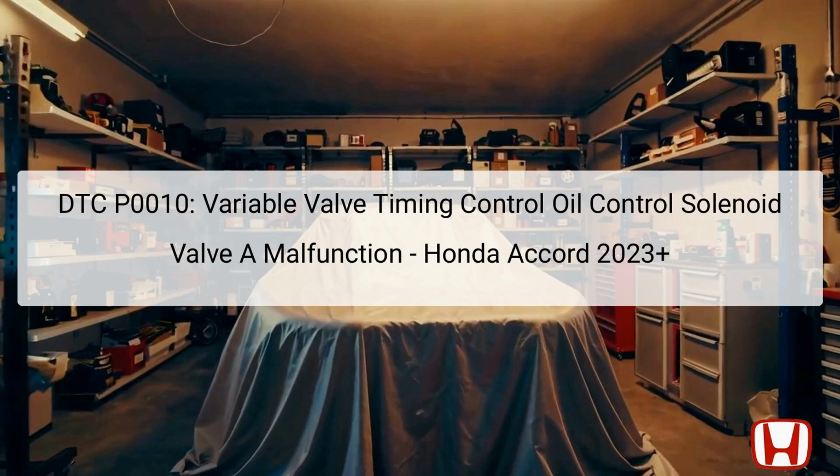DTC P0010 indicates a malfunction of the variable valve timing control (VTC) oil control solenoid valve A in the Honda Accord 2023 and newer models. This issue arises when the return signal from the VTC oil control solenoid does not change as expected with the output signal from the powertrain control module (PCM).